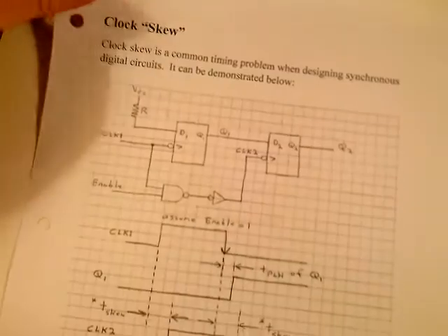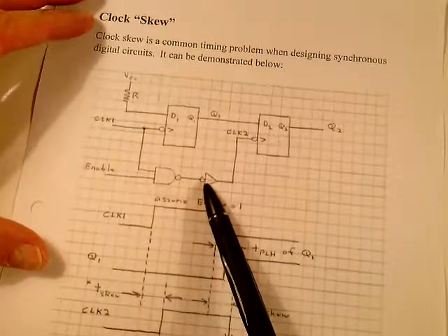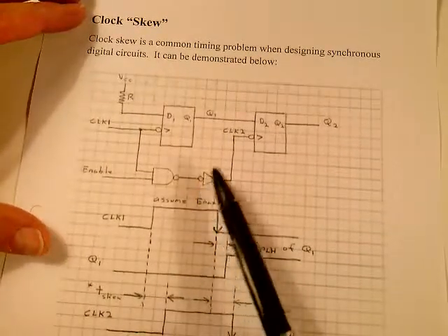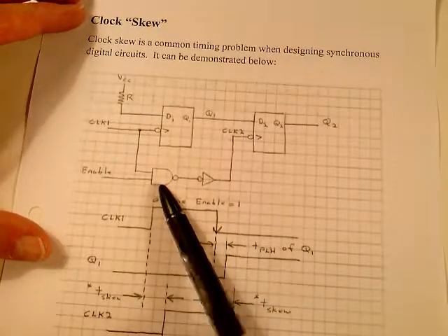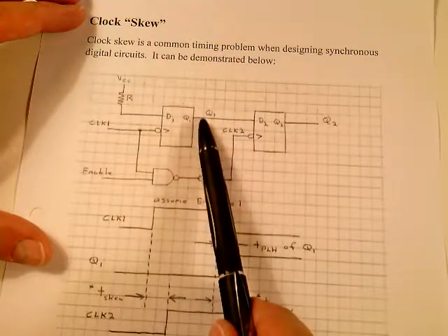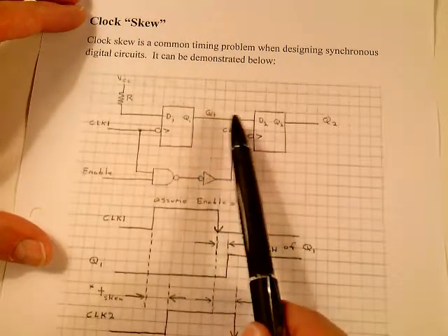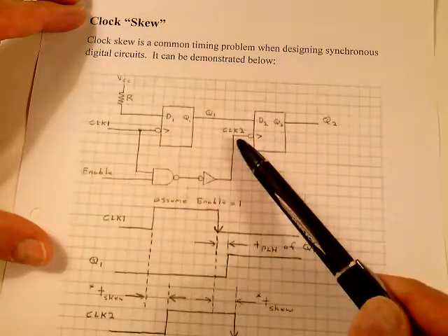Why? If you go back and take a look at the circuit, the reason I put 2 in is that one compensates for the delay here, another one compensates for the delay there. The propagation time of an inverter is roughly the propagation time of a NAND gate. You can look it up. So if I put 2 inverters in up here, it'll slow this 1 down so that it won't be already set up when this clock edge comes.